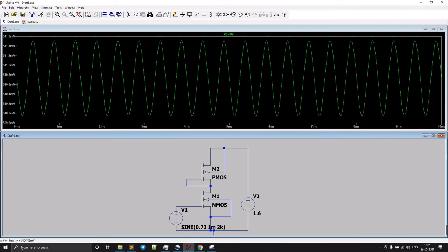So this will be from 510.7 to 511.6 millivolt. That means just a 1. Okay, so we are almost getting the gain of 1, but that's too less. So we need to build something extra, that means some advanced version of these kinds of circuits, because we are getting the gain very less.